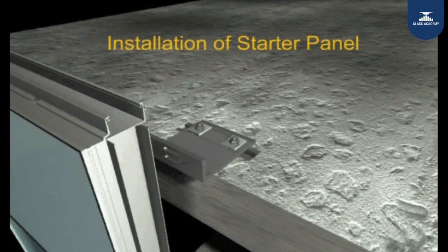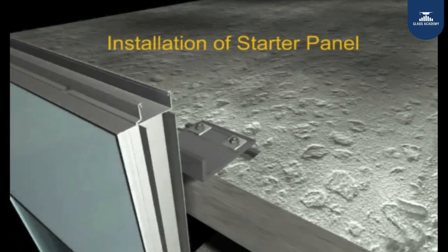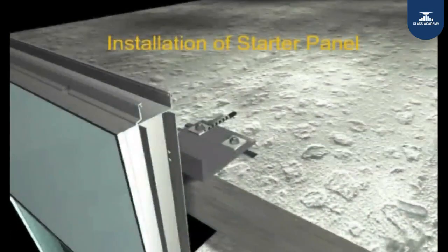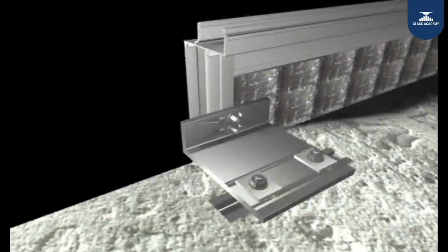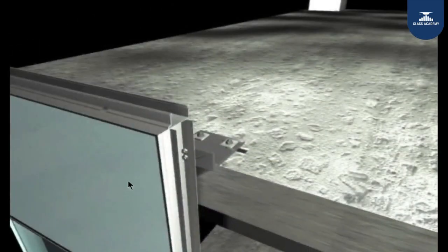Now, the panel comes from the factory fully done, you put it there and you drill 2 bolts. It is a simple form of fixing the system. So, you see you put 2 bolts, you attach them, you are done, that is it, the panel is installed. What you see here is a gutter head, what we saw as the split mullion, it happens slightly above the floor level. This is a mullion waiting to receive the other panel.